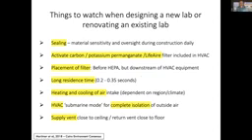Use activated carbon, often in combination with potassium permanganate as an oxidizing agent, or the Live Air system for filtration included in the HVAC system. This goes away from the previous standard, which was pre-filtration and then filtration to remove important contaminants, such as microbial organisms, through HEPA filtration. The placement of the filter must be before the HEPA, but downstream of the HVAC equipment.